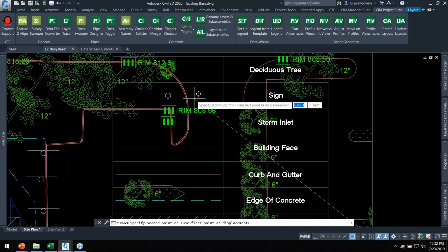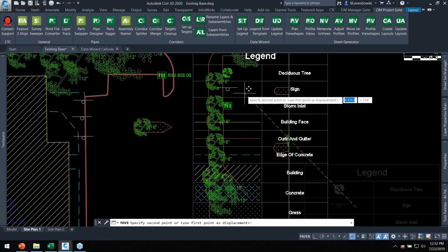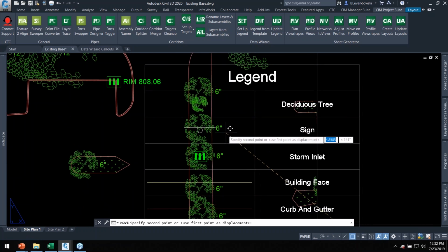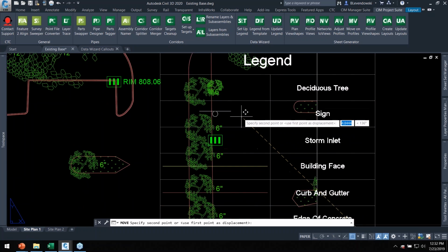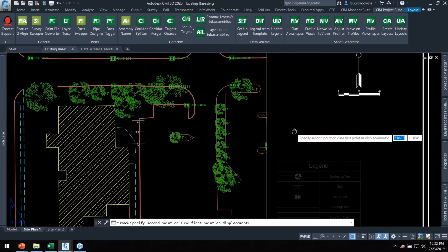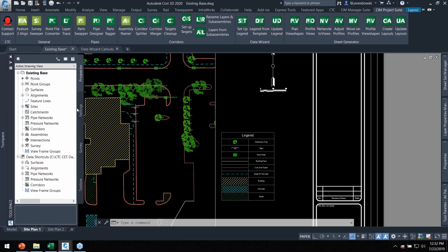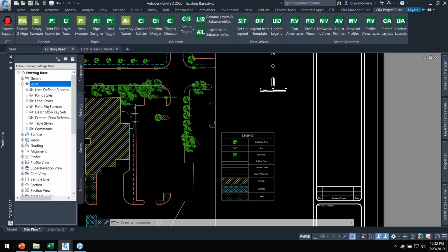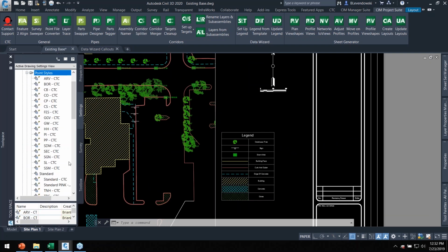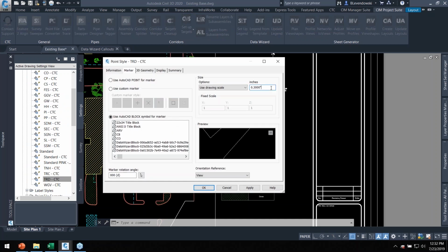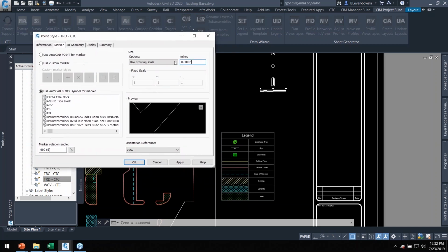The catch basins. And of course the trees, we've got a description key scale factor happening there. So what it's going to do is take the standard size found in the point style and apply that right here. And you can simply play with the value. I'll just mention it because it's worth noting in your point style right here, and that will affect the size of the symbol right here.